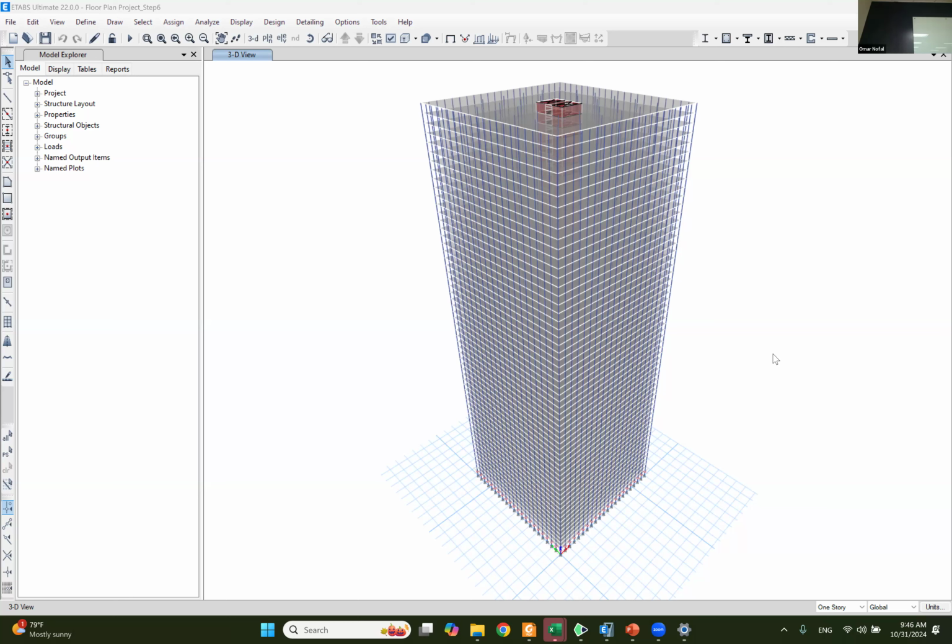Once you know this base shear at the building, you can identify how this is going to impact your building. Can you imagine, you have your building and you shake it very hard with a force from the base, what is going to happen to the building? Okay, then ETABS is going to run a dynamic analysis based on the base shear that it has at the base, and then find out all the internal forces in the columns, the drifts that are going to happen, and everything.